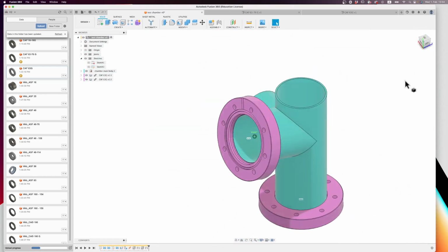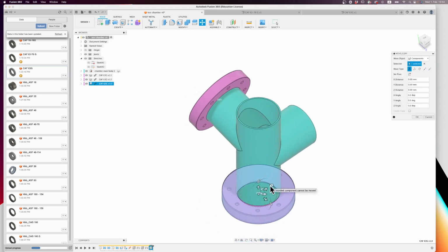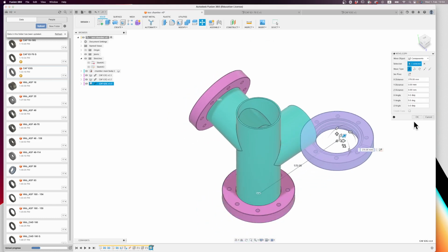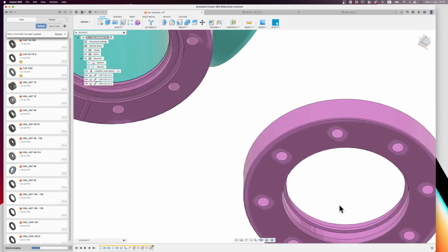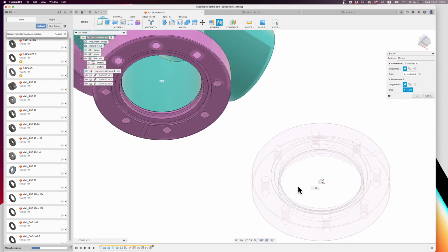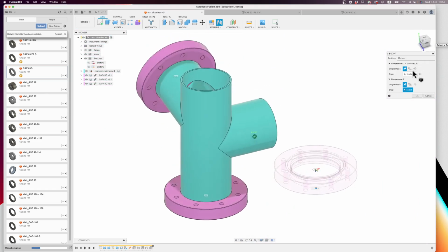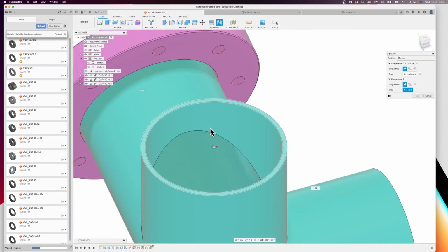Yeah. And I'm just going to repeat that 2 more times, and then I'll quickly show you how to do the design drawing for that, because that's what you're going to send to your manufacturer. Because it's nice that you send in the CAD model, but you're also going to need to specify tolerances. You're going to need to specify what's important and what's not important, and if you have any tolerances. And you need to communicate materials as well, and we'll get to that in a second. Then I'm going to switch off the component coloring, which is currently switched on.